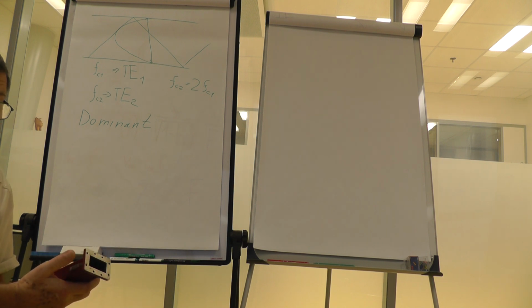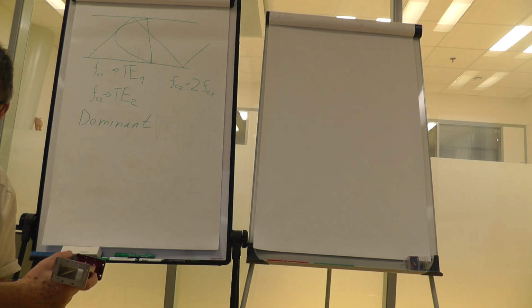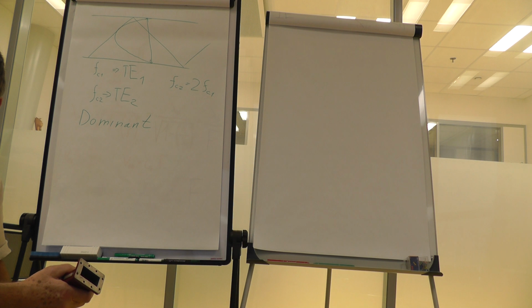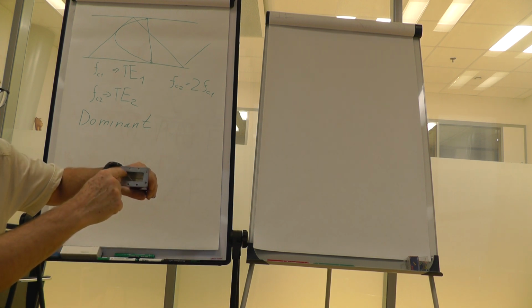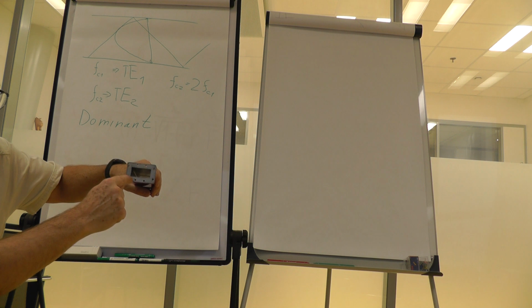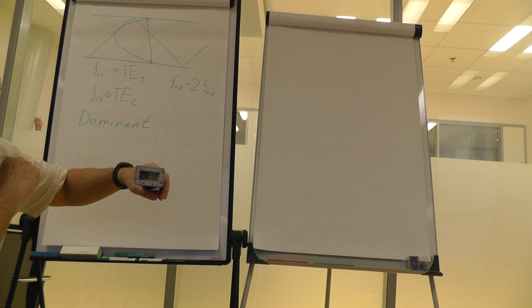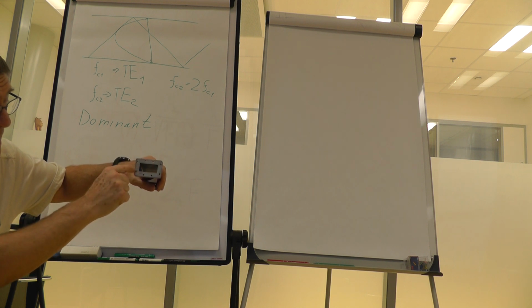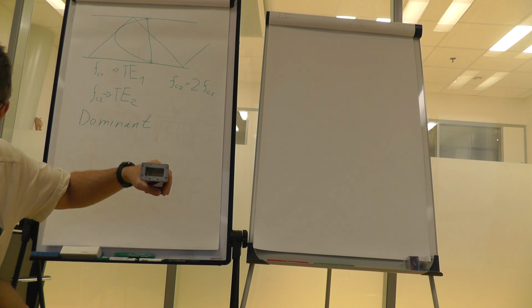Now with transverse electric modes, there must be at least one of the indices non-zero. So we could have a TE10 mode, which means there is 1/2 wavelength of the standing wave over this longer dimension, or we have TE01, which would require higher frequency but could exist, and it is just turned 90 degrees, so there will be 1/2 wavelength within this direction.